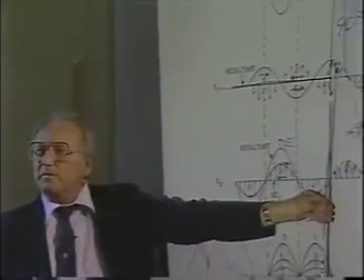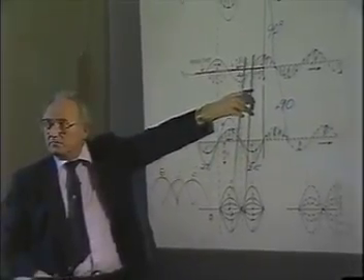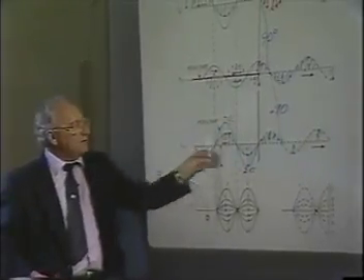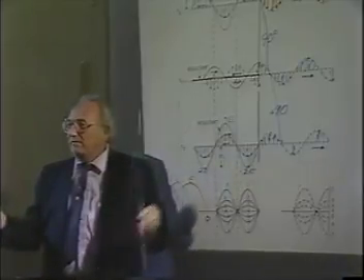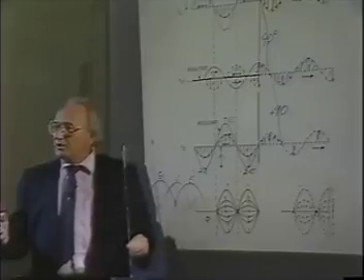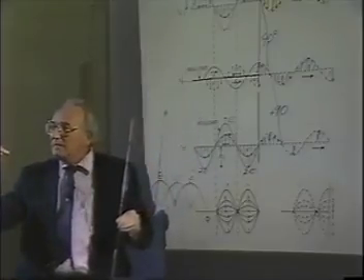What happened when the electric field went out and hit the short circuit? It reflects 180 degrees out of phase, right? What happened when the electric field came out and hit an open circuit? The reflected wave, instead of reversing, went up to 2E, didn't it? At the open circuit.